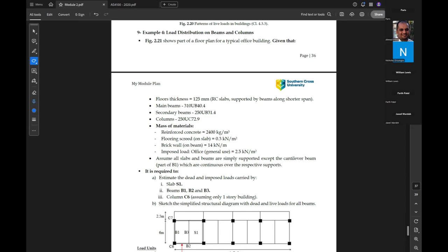For the first question, it says it's an unbraced beam column member. I was just wondering how we know what effective length to take. Like, you know how you showed us the table that shows the different effective length factors, like 1.2? Do we need to consider that in the first question of the assignment?